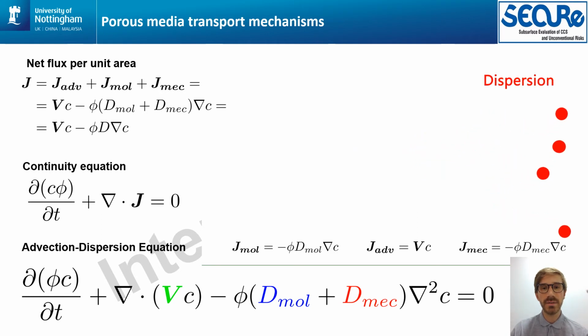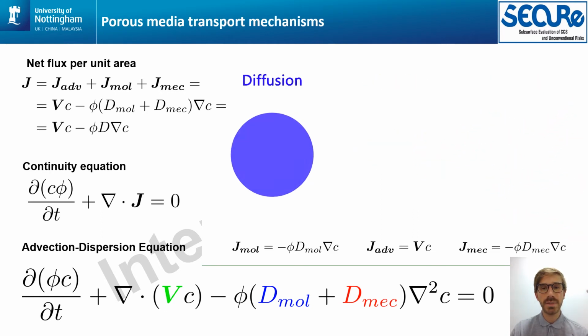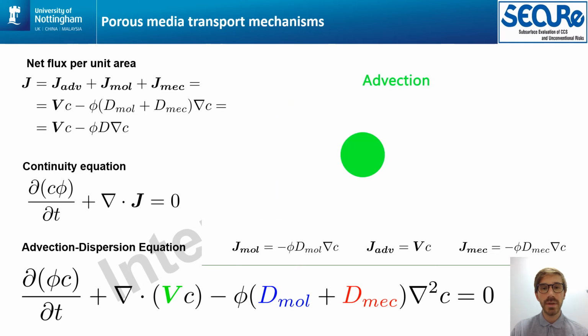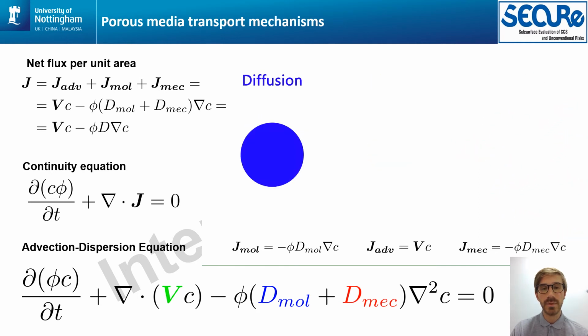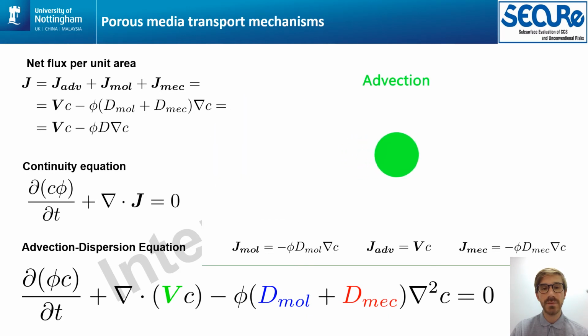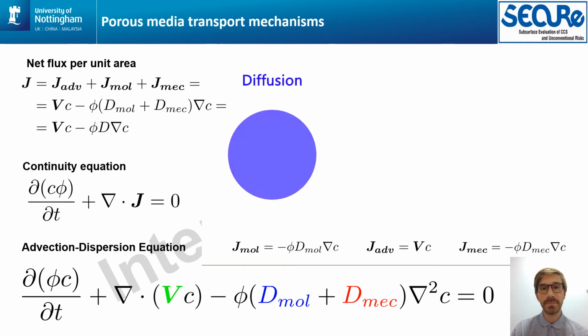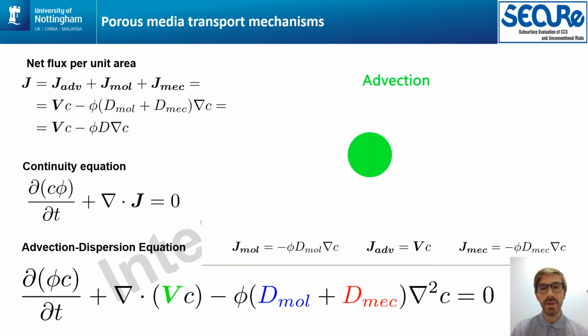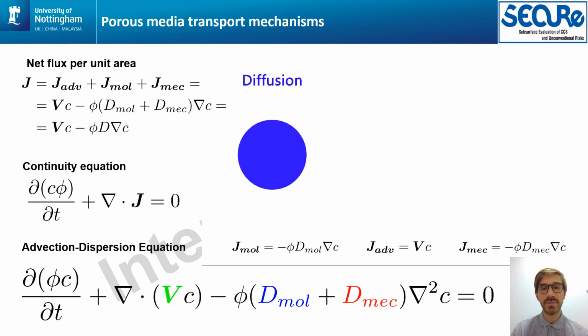Considering the classical continuity equation and substituting the concentration C for the density ρ and the flux per unit area J with the Darcy flux ρV, we obtain the advection dispersion equation for the case of no source or sink terms within the domain. By including this simple mechanism with constant dispersion in our model, we enable the study of the effect which heterogeneous velocity fields have on transport.